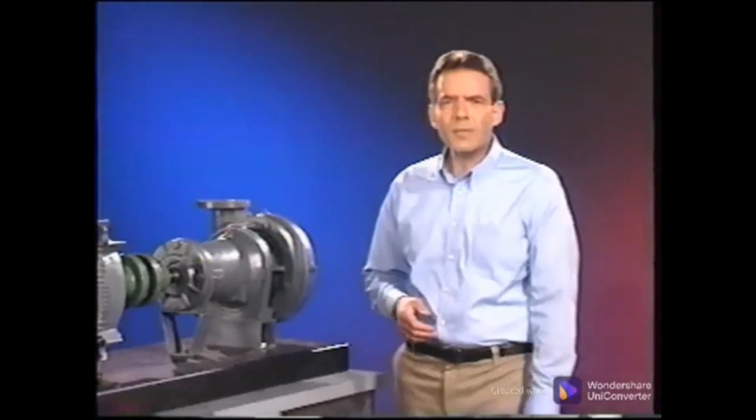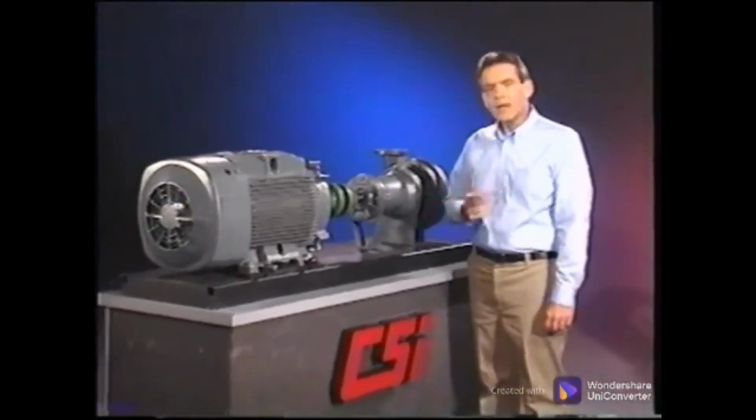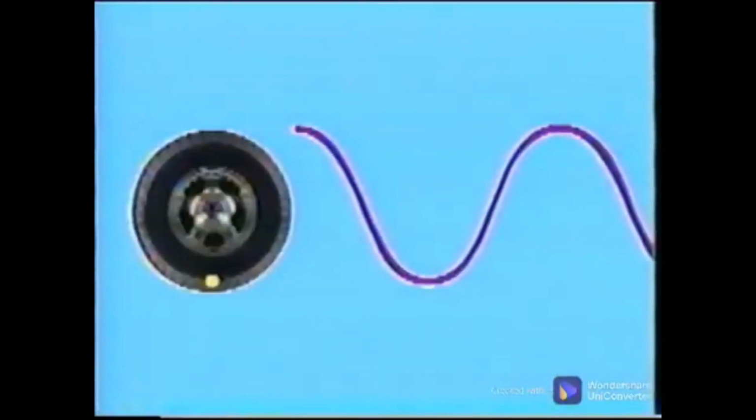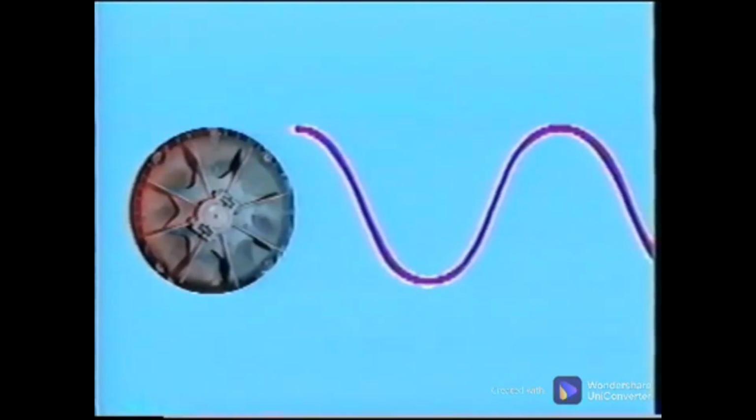We have used the unbalance of an automobile tire in the waveform and spectral data examples. Because we are really interested in industrial machinery and equipment, let's see how this applies. The same waveform and spectral data could be generated from industrial machinery that has an unbalanced problem. If the machine has other sources of vibration, they too would show up in waveform and spectral data.